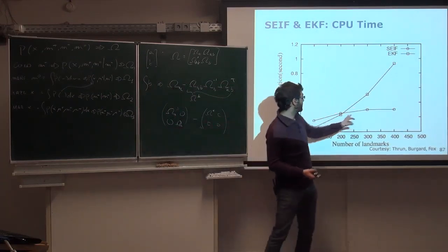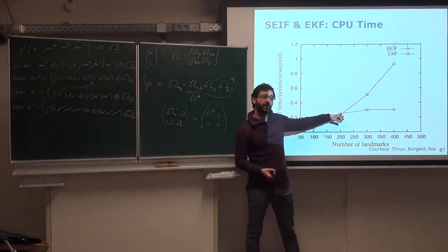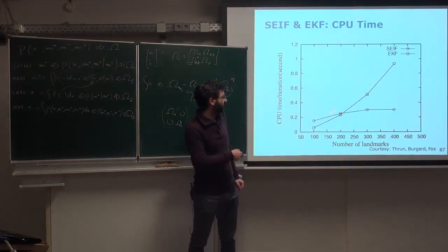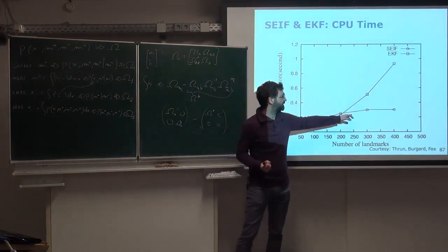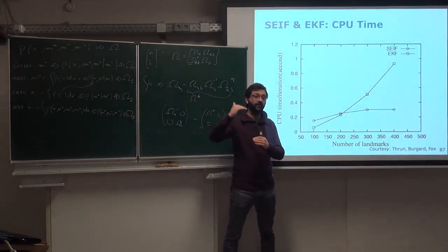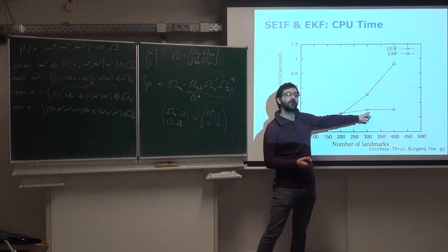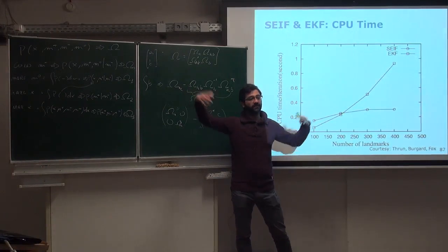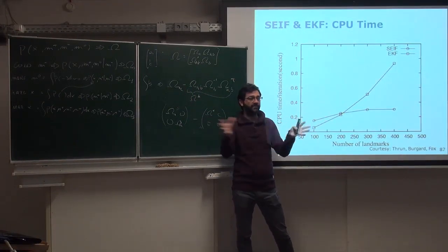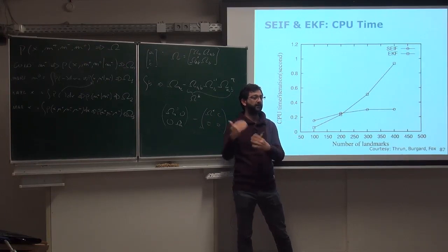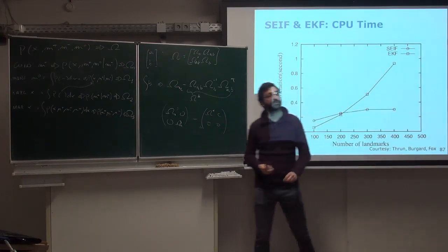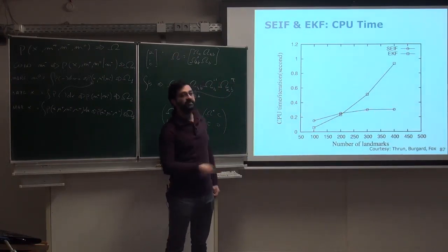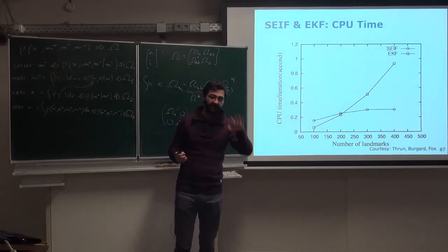And that's because you will always have an increase of computation because of part of the overhead and part of the amount of landmarks that you will keep in the window. So you will reach at some point a critical number of landmarks, and then they will be so spread around that the number of landmarks that you see at one instant of time is actually kind of constant. Everything is bounded, and then you get a roughly constant computation. This will still increase, but very lightly and smoothly.